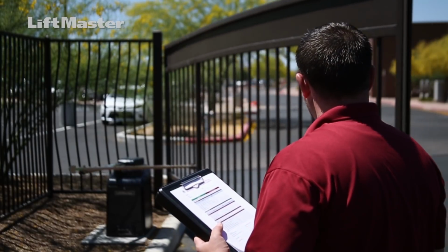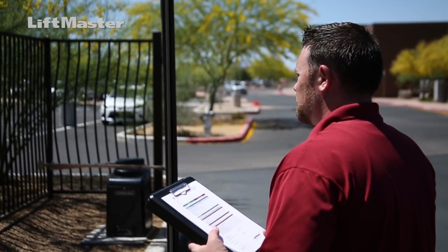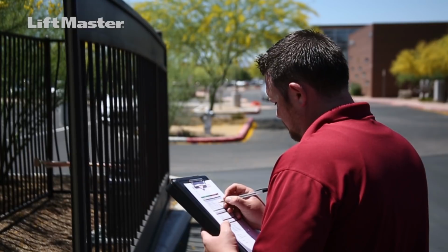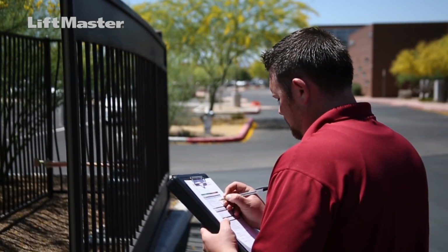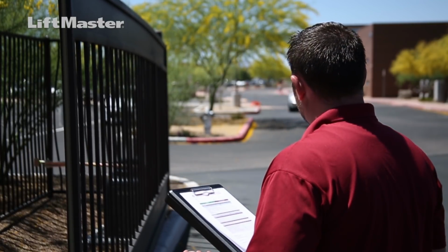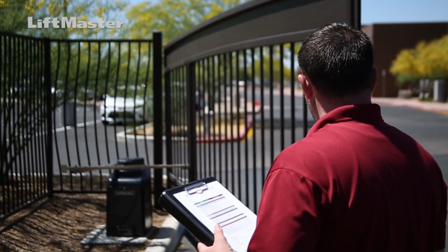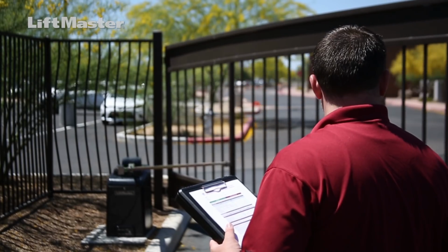Do not repair a gate operator manufactured prior to the year 2000, as they may not have inherent and external entrapment protection systems. Operators manufactured between the years 2000 and present may be serviced if monitored external entrapment protection devices protecting all entrapment zones are properly installed.